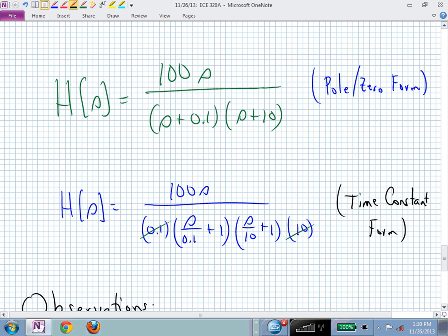So you look at your poles, how many you have. You have 2. You compare that with how many zeros you have. You have 1. And I refer to this as your pole zero excess. You have 1 more pole than you have zero. And at high frequencies, this system is going to look like something over s. It's going to look like a single pole. When those 3 things become active, which is what they're going to be at high frequencies, you'll have a pole, that'll give you minus 90. You have a 0, gives you plus 90. Oh, now I'm at 0.